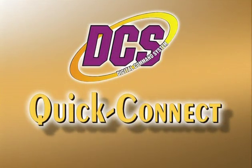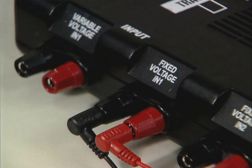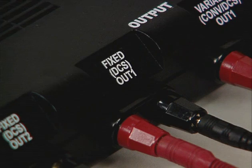Here's how to get started using the MTH digital command system. Place the track interface unit between your power supply and the track. If you plan to run only in command mode, plug the black and red wires from your transformer into the TIU's black and red banana jacks on the fixed voltage in 1 channel. Connect wires from the red and black fixed out 1 banana jacks to your track or lock-on.